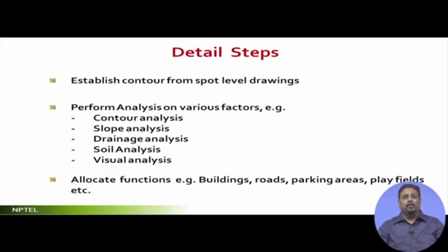First step is that you establish contour from the spot level drawing. Now this is the first step of the landform design, which you are not doing at the design stage. If you recall, when I was saying that when you start doing your site analysis and investigation, 50% of your design decisions are taken there. So establishing contour from the spot level drawings is the first step of the landform work. That means you are trying to understand the levels of it, and this task has already been undertaken during your site analysis time.